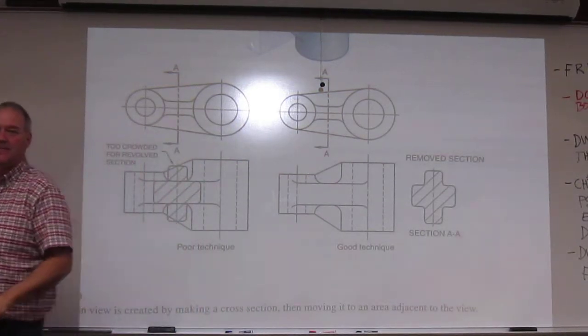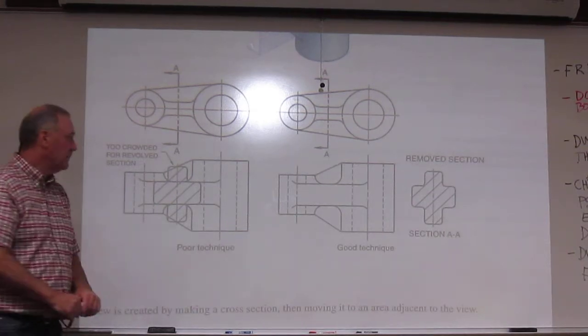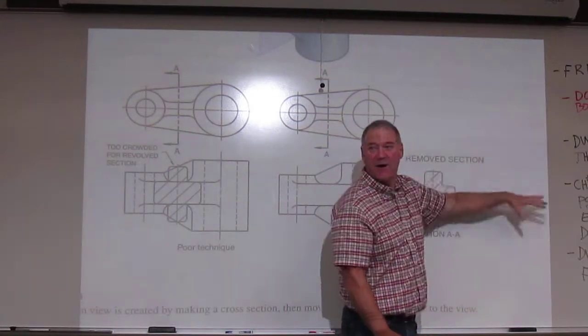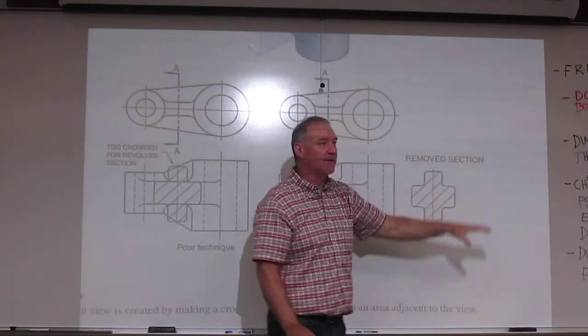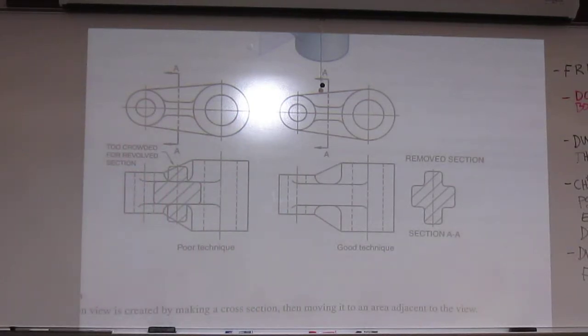Does it have to be lined up? No, it does not. It must be just adjacent. I would take it and stick it in the bottom corner, the top right, or somewhere off here where it's not confused with this thing being turned. They've got the AA, they've got the cutting plane line, they can find it, they can then make that connection. But we want to make sure it's not in that rotation sequence that we use.